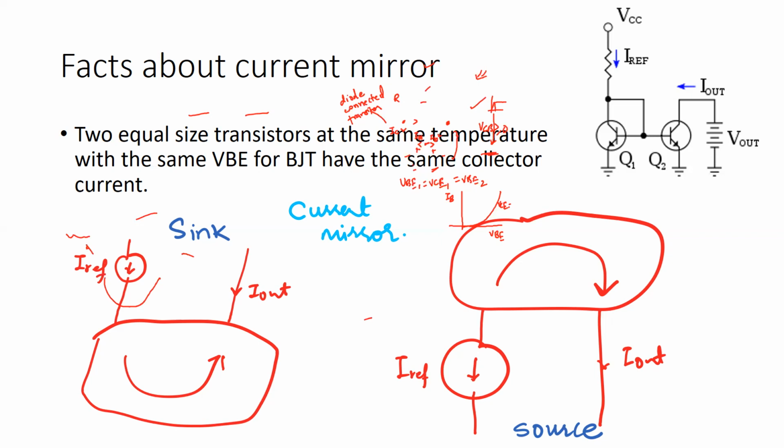So when you see such an arrangement, it is called a current sink. On the other hand, if you are given a current sink at the input side, then the current mirror acts as a virtual short, reflecting this current at the output side, and therefore we obtain a current source. So here we obtained a current source. Here, look at the direction, we obtained the current sink. So that's the principle of it.